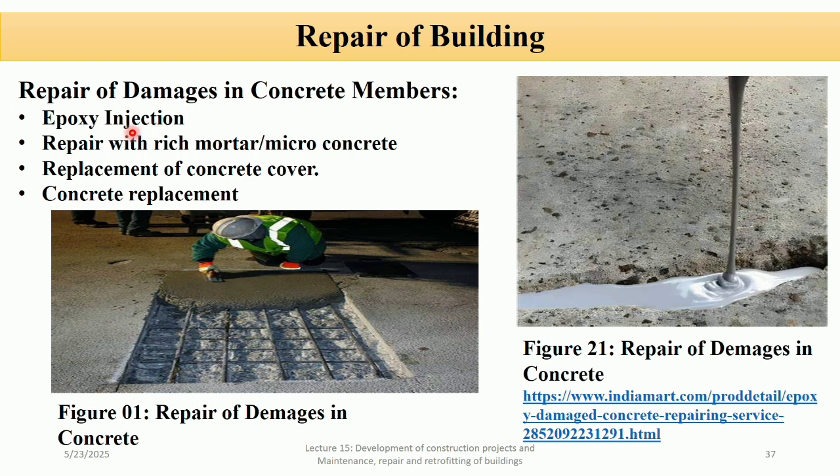It is a process where low viscosity epoxy resin is injected into fine cracks under pressure. Then repair with rich mortar or micro concrete, a high strength mortar made with a higher cement content than normal mortar, used to fill damaged areas. And replacement of concrete cover.